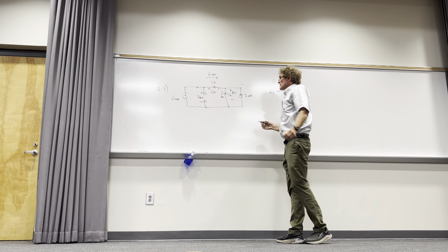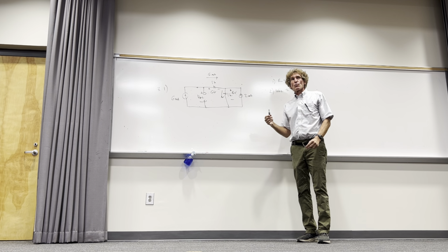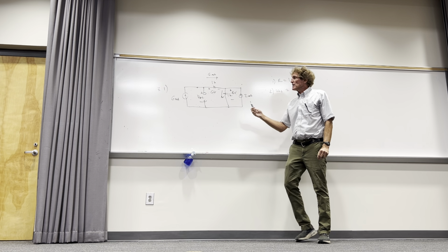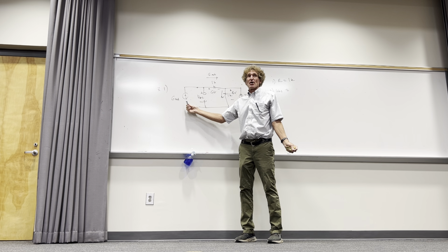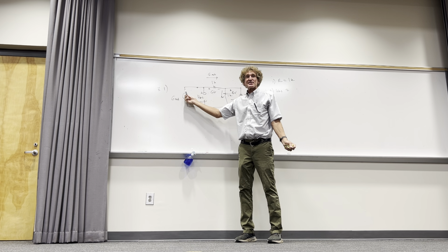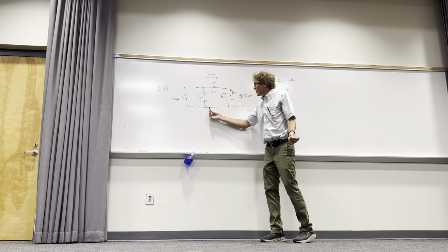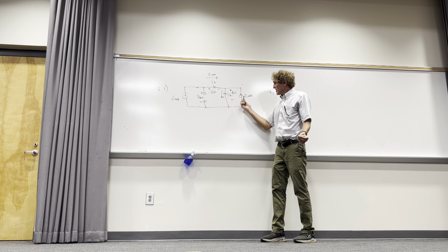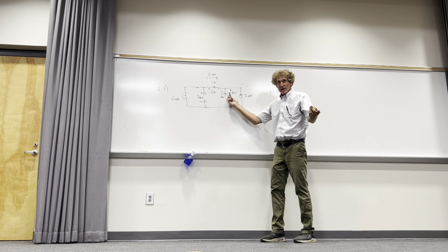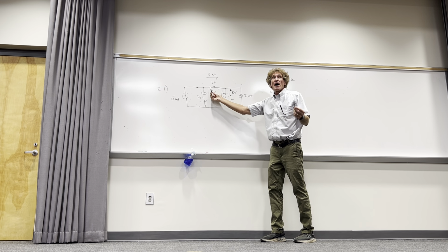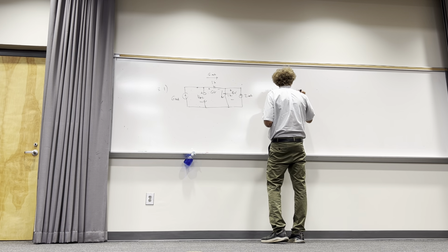VOC? Now, what did I tell you to do last time? Start where? Anyone? Negative terminal, right? And can I go this way, class? Yes or no? Not maybe. Now, if we don't know this voltage, that's a current source. We don't know what voltage is across it. You with me? You can't sum voltages around a current source. We don't know the voltage. Which way do we have to go? Can't go here. So I start at the negative. What does this say? A voltage increase of 8, and this is a voltage of 14 volts, right?